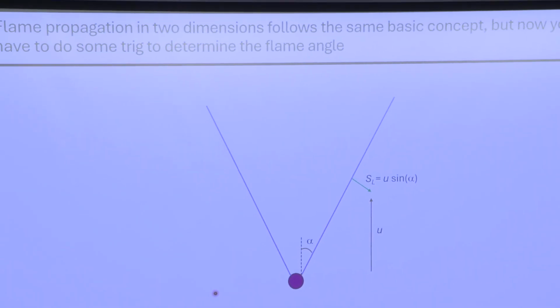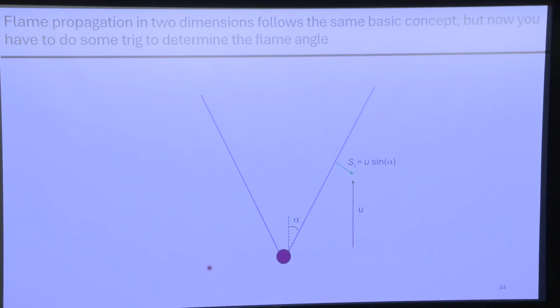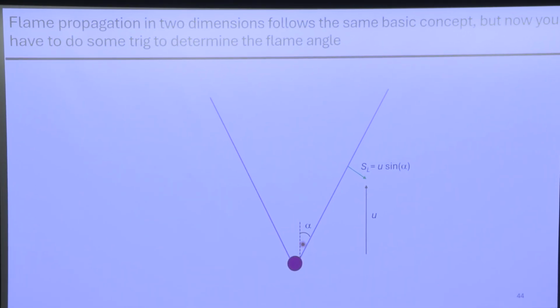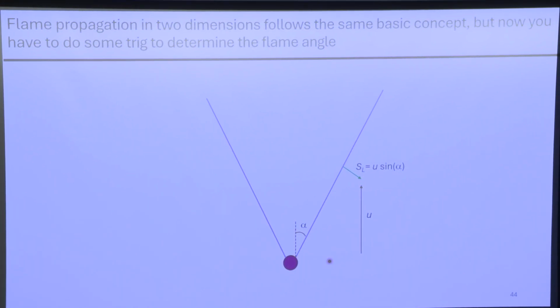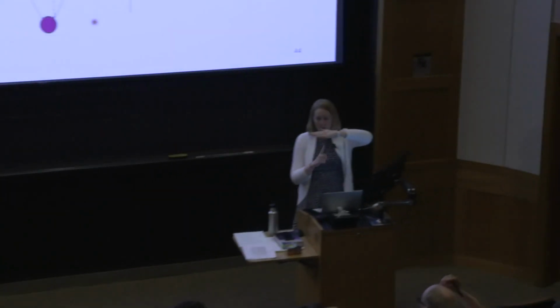We can see this in two dimensions by looking at a flame stabilized on a rod. Here the flame is stabilized at some angle alpha. If the kinematic condition were met in one dimension, if S_L were really equal to U, then the flame would be sitting horizontally, right? Because along the length of the flame, it would all be equal to the incoming flow velocity. But if combustors had to do that, they'd be very slow, right? So we don't rely on that.